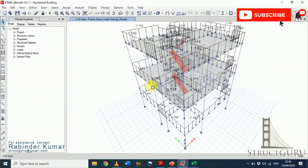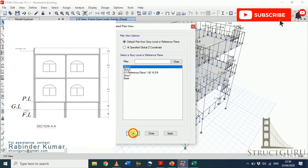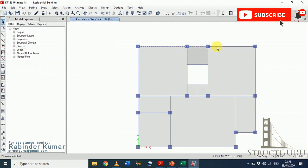Switch to the 3D mode. As you can see, we have successfully applied wall loads. Now we have to change the wall load at roof level because our parapet wall is of 3 feet. So go to the plan view, story 3, click OK. Choose one story from drop down list. Click the exterior wall.